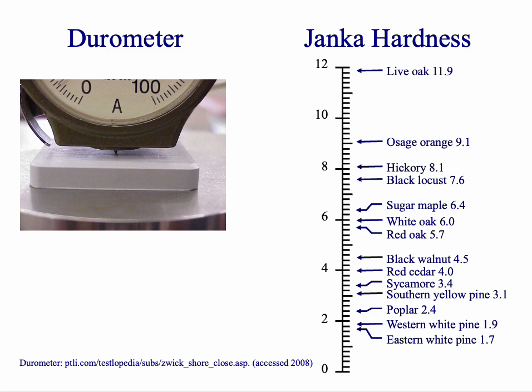The strange thing about the Janka hardness test is that the force has different units in different countries. Pounds in the United States, newtons in Australia, kilogram force in Sweden. The values shown in the table are the side hardness, where the ball is pressed into the side grain, not the end grain. Janka hardness is used mostly for flooring as a measure of scuff and gouge resistance.